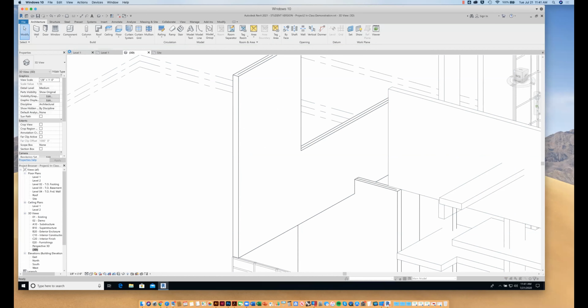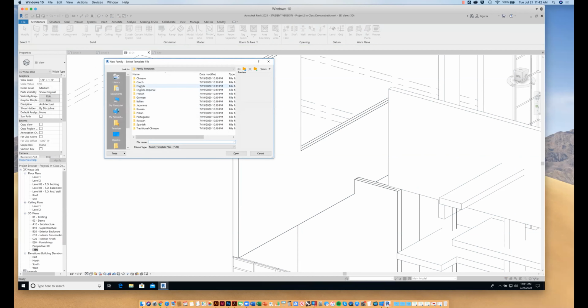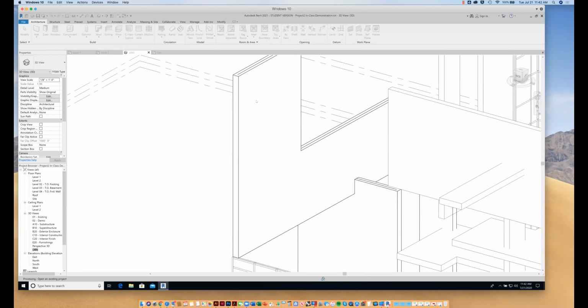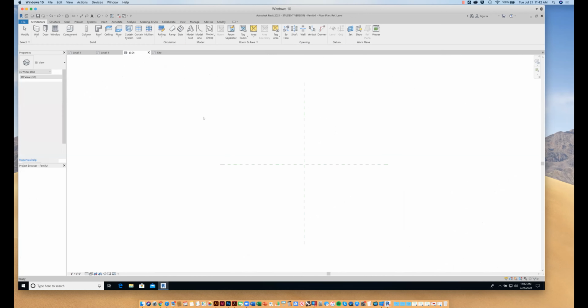I'm going to say New, New Family. I'm going to create a new family of English, English Imperial, sorry, feet and inches. I'm going to go to Reveals, or sorry, Profiles. Profile. And it's going to open up the profile page. Now here I can create a new custom parametric family.